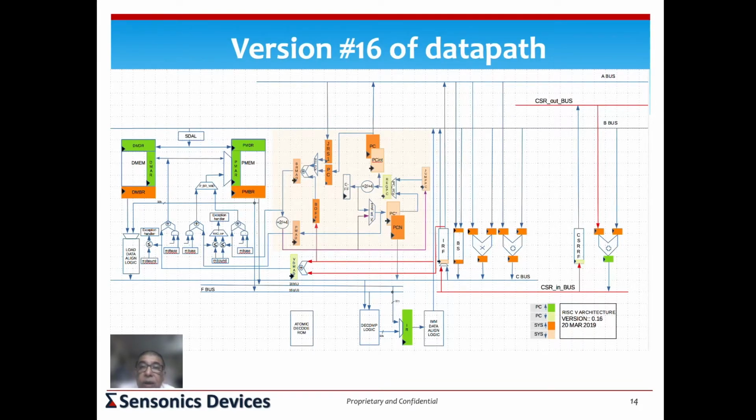So every piece of logic here has a data port, some data coming in. If you look at the instruction for integer register file, I have not shown that here. There is an output. As you can see here, the IRF shows that its output can go to one of two buses. It can go either to the B bus or to the A bus. Does it mean there are two different ports? Can it happen simultaneously? You have to define that. In our case, we defined it not to be simultaneous. So it means that there is only one output that you can read.